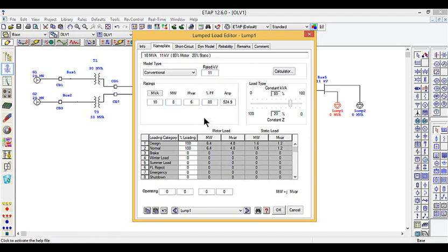And 11 kV. You can also assign different types of load. This helps in scenario analysis, like what is the load in winter, what is the load in summer, what is the load in emergency conditions, that is very necessary loads that you need to run. And one more thing that you need to specify is the load type. Now we also need to discuss what are different load types.